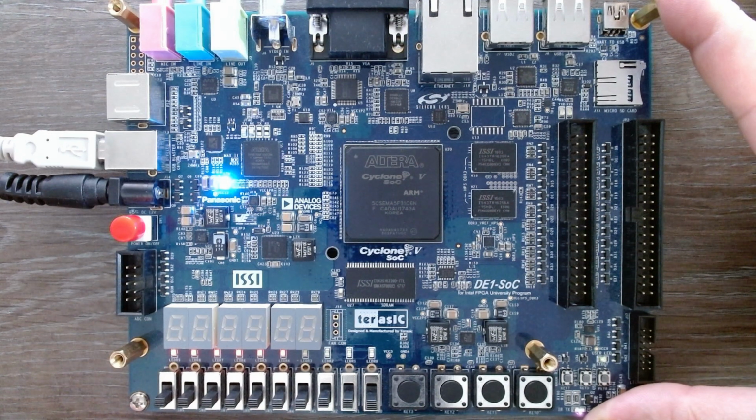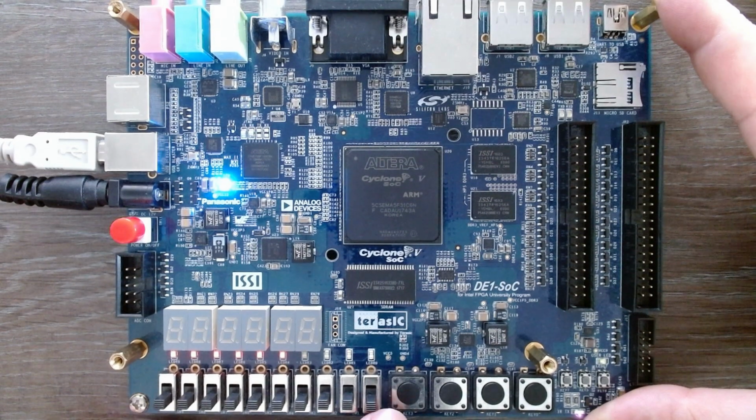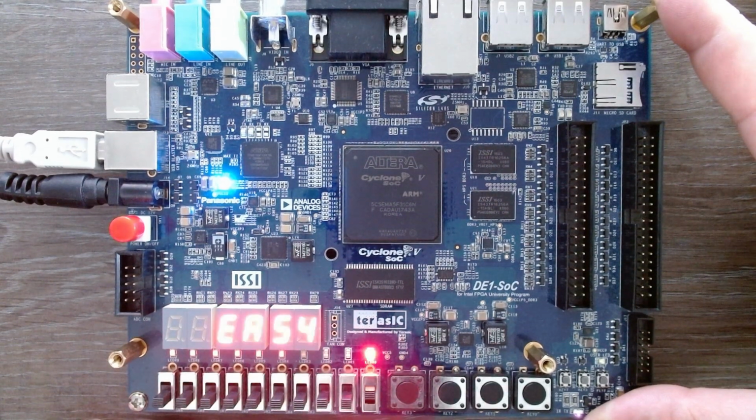This is how the AZ-FPGA state machine should work on your development board. Initially the design is on reset. After we make reset N equal 1, then the state machine should start working. As you can see, on the LEDs we have the current value of the state. On the 7-segment displays, we can see how the AZ-FPGA text is being displayed during the state machine changes.